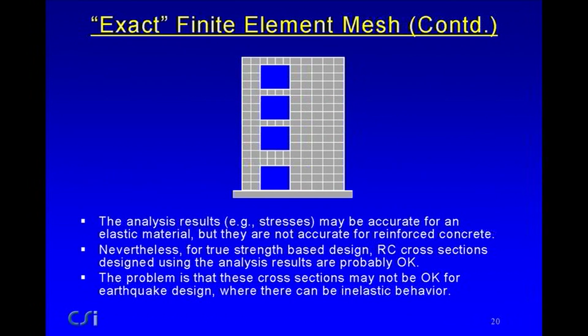So, the stresses may not be accurate. The second point, nevertheless, for true strength-based design, reinforced concrete cross-sections designed using the analysis results are probably or almost certainly okay. The problem is if you're talking about earthquake design, these cross-sections may not be okay for earthquake design where there can be inelastic behavior.